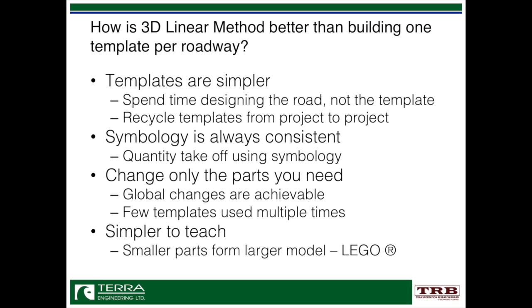The section of tollway, of PCCP and a subbase and a base course, has been around since the 50s. So that section is not going to change anytime soon. You can use that template on any tollway project. A curb profile in the state of Illinois hasn't changed since the concept of curb existed, because Illinois doesn't change very often. So that template, you build it once, you use it thousands and thousands of times on multiples of projects. So you spend the time creating the road, not the template that feeds into the road.